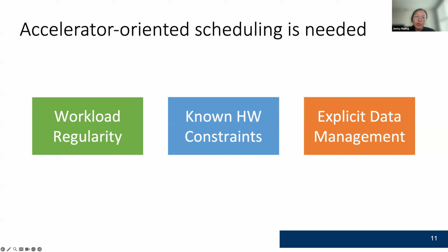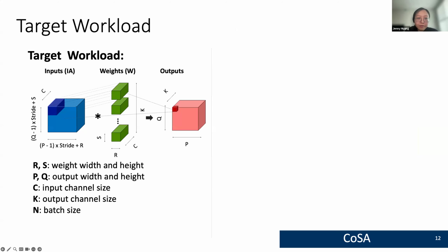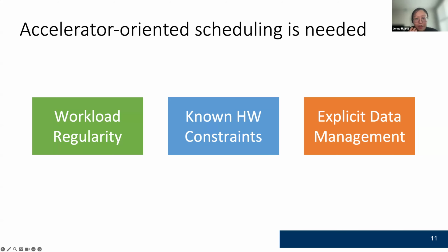Basically, we would know where the tensor is stored in different buffer levels, unlike in a cache, which is implicitly managed by the hardware itself. However, existing approaches always treat the hardware as a black box, and just rely on feedback to generate a high performance schedule, without considering any of this information from the ML algorithms or the ML hardware.